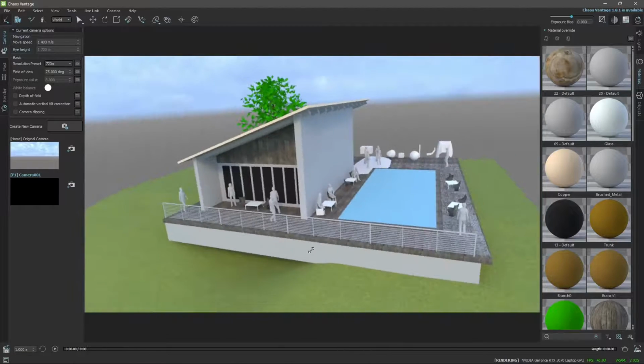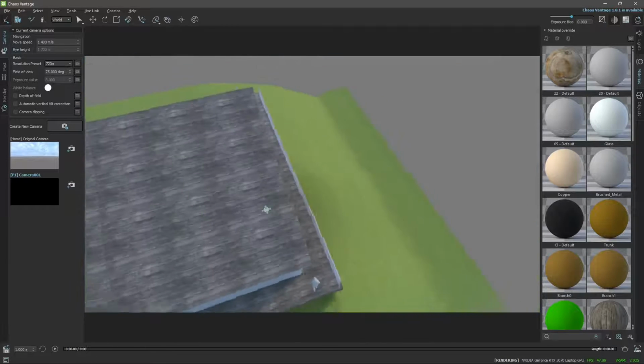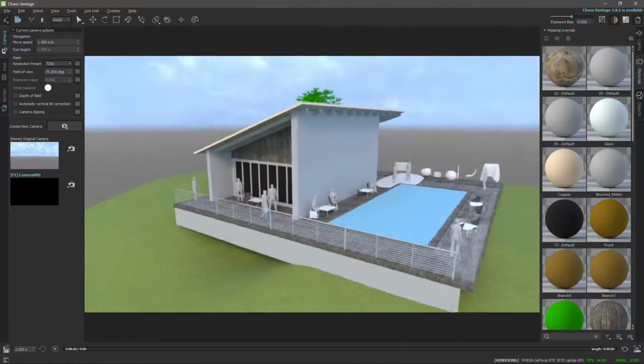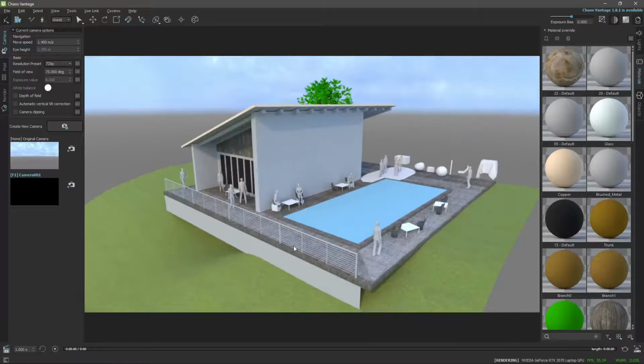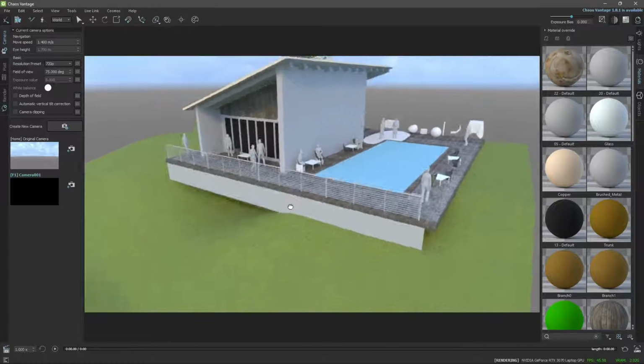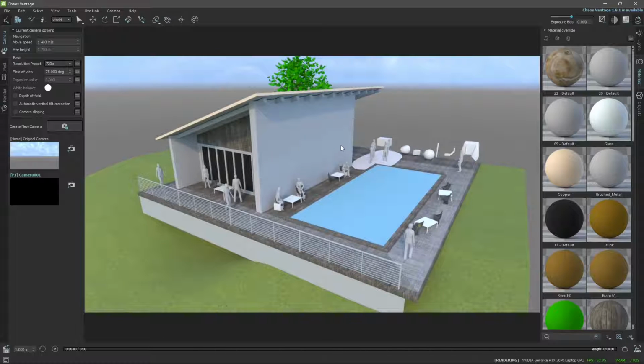Now, one thing I don't really like is when I hold Control and press the scroll wheel, it's gonna rotate the view. So be careful not to press Control and click on the scroll wheel, so you're gonna do this strange rotation. But if you hold the Alt key and the scroll wheel, you're gonna orbit around. This is also really useful if you want to move around your scene. So Alt and click on the middle mouse button, your scroll wheel, to orbit. So basically anything passes through the middle button of the mouse or the scroll wheel.